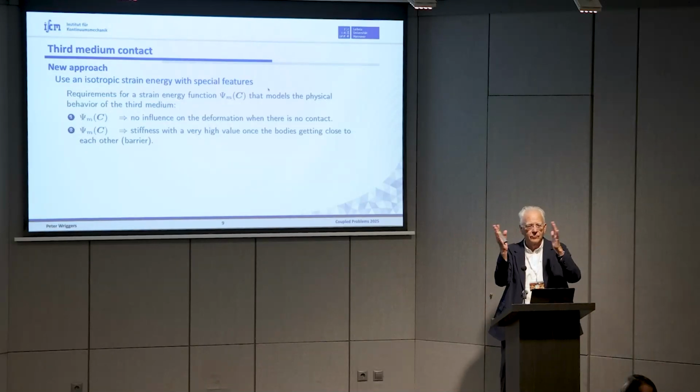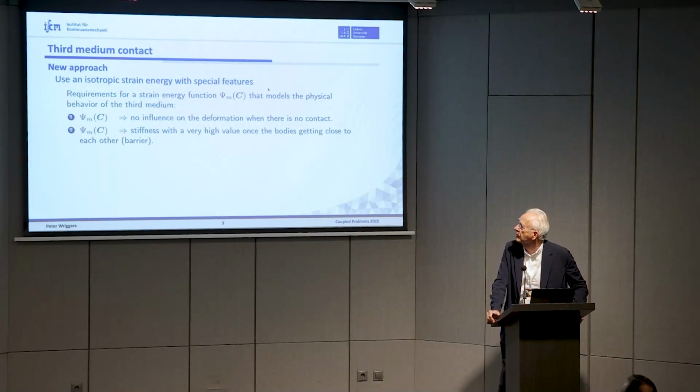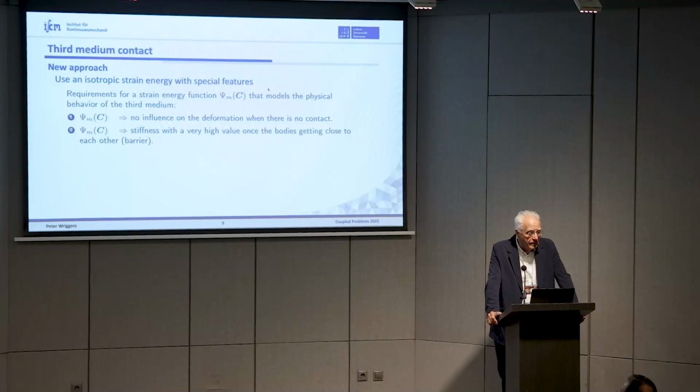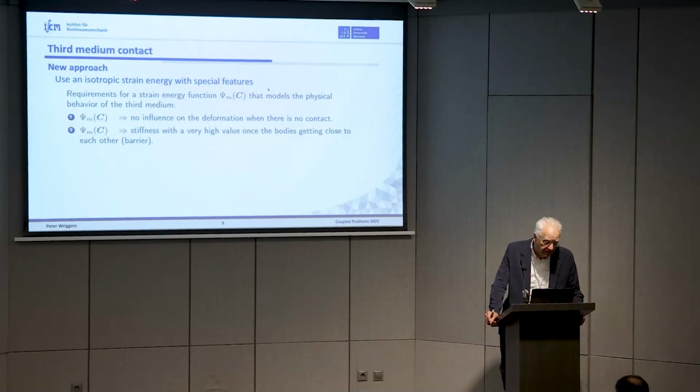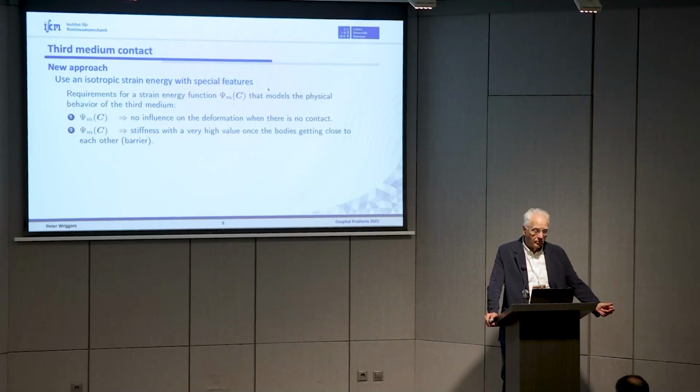Forget about this computation of the anisotropic part, which makes a problem. So the anisotropic function, of course, has some requirements. First of all, it should be designed so that there is no influence, as I said before, on the deformation of the third medium when there is no contact. And the other one, the stiffness should be very high once the bodies get close to each other, the barrier method. And here you can see what it means.